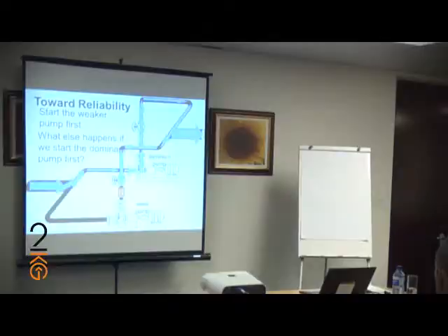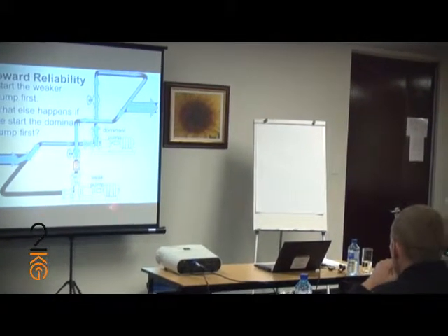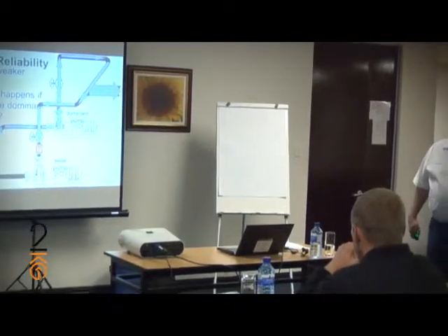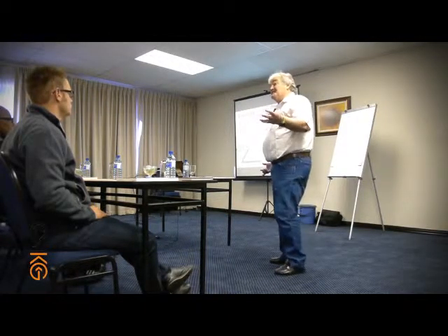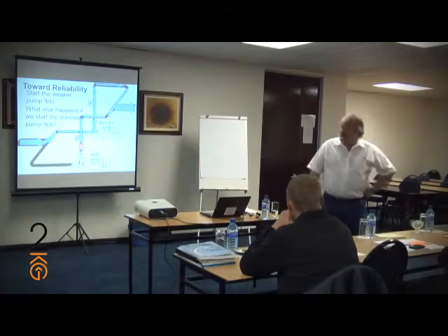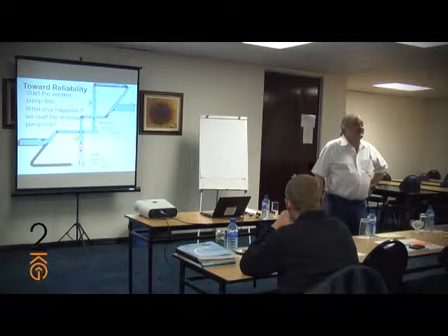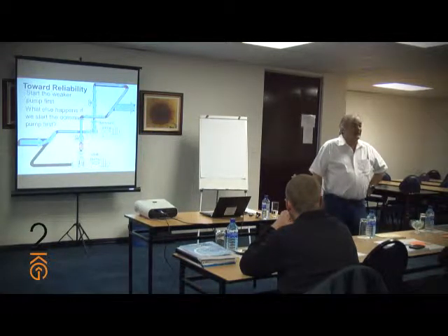So what is the weaker pump really going to contribute to my process? Absolutely nothing. So after this pump deadheads for 3 or 4 weeks, the seals and the bearings will fail from vibrations and distortion, and this pump becomes a high maintenance pump. And then somebody says, send those mechanics to a pump rebuild class so that they'll learn how to rebuild their pumps properly.